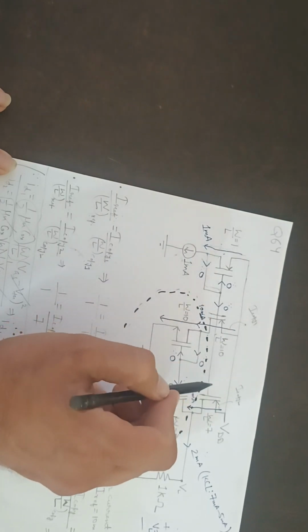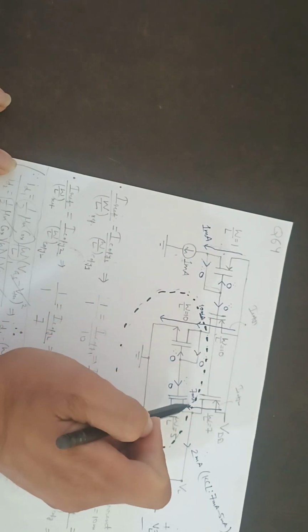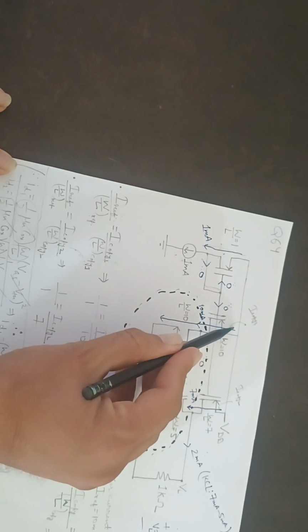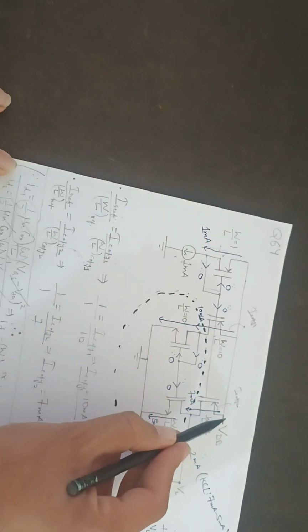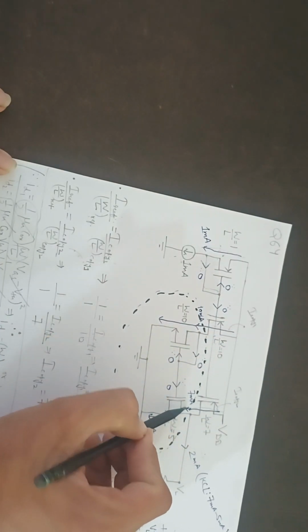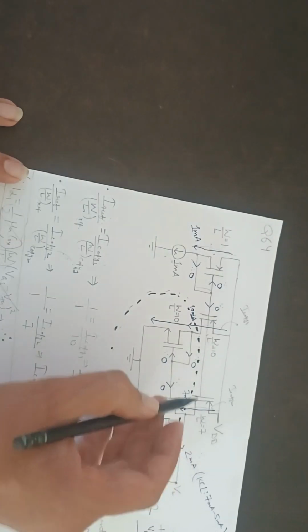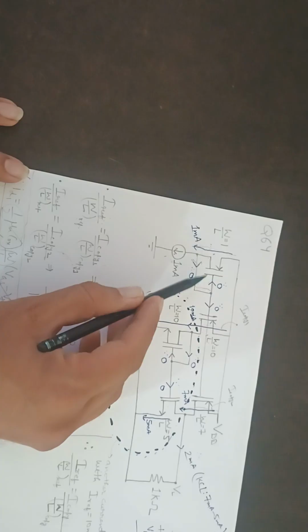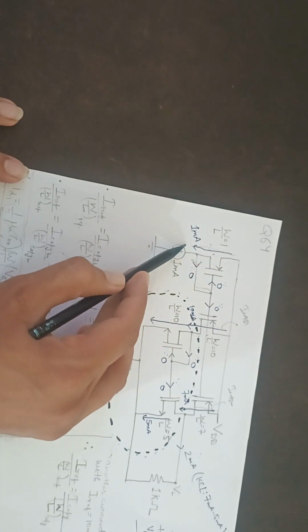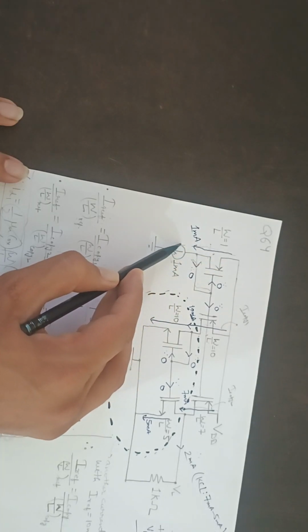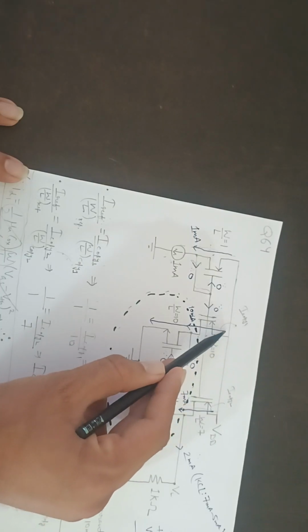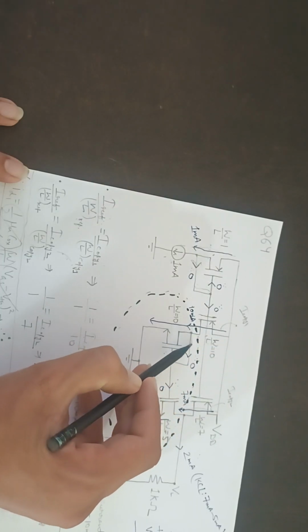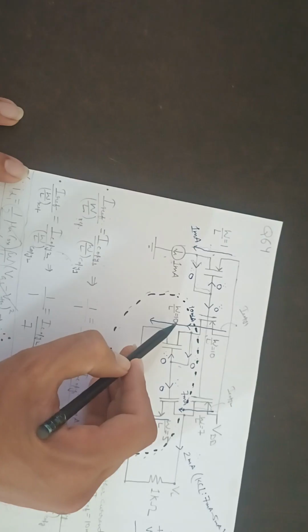Similarly this is 1, so this will be 7 milliampere. So this current is coming as 10 milliampere, this current is coming as 7 milliampere. No current can go into the gate, so no current can go in this one, so the entire I1 milliampere will flow down. Similarly here also this 10 milliampere cannot go here, so it will go down only.